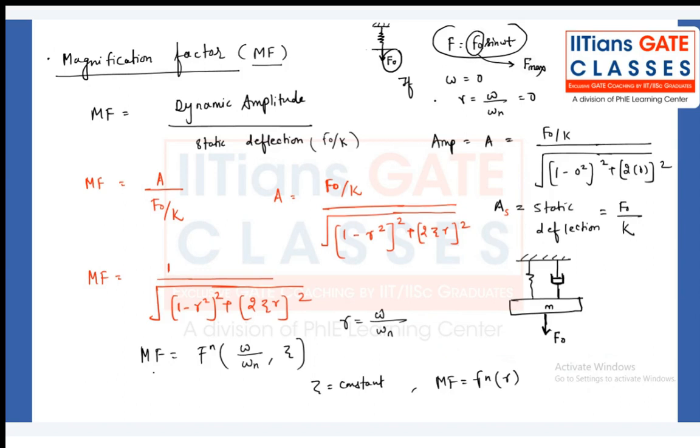This is the maximum value of this force. If I apply this maximum value of the force to the machine, the machine has some stiffness. If I divide F max by K, I will get some deflection. We would think that if I apply this much maximum force, that could be the maximum deflection possible in a running machine.